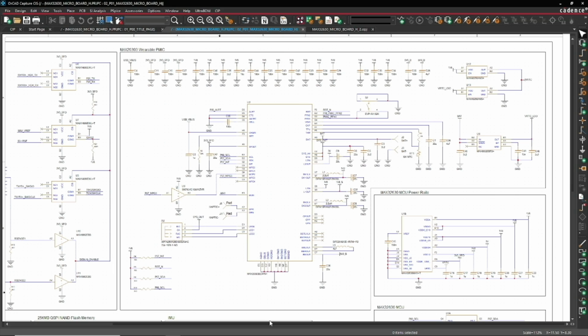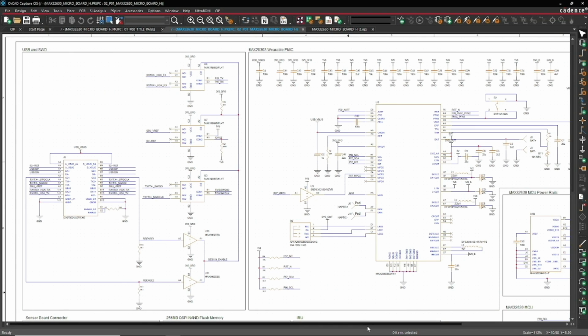Here we have the PMIC, or Power Management Integrated IC. The capacitors need to be close to the integrated circuit. Just below, we have the power section of the microcontroller unit, intentionally separated from the control section of the chip. Let's see if there are any other possible power devices like the USB powered areas. Alright, sure enough, the USB-C protocol is used here for also getting power into this device.